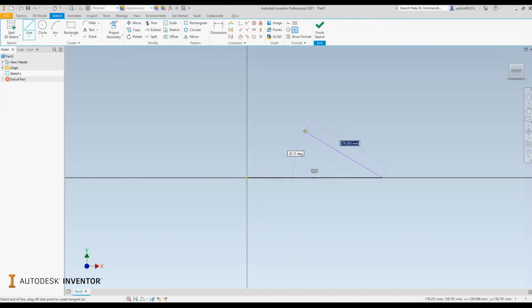And once I've placed my first segment, I can continue placing additional lines. Simply using my tracking on my screen gives me an indication of where my line is seated, and as I head over to a complete vertical position, it infers a 90-degree constraint. Essentially what this means is the vertical line will always be perpendicular to the horizontal line at the bottom.